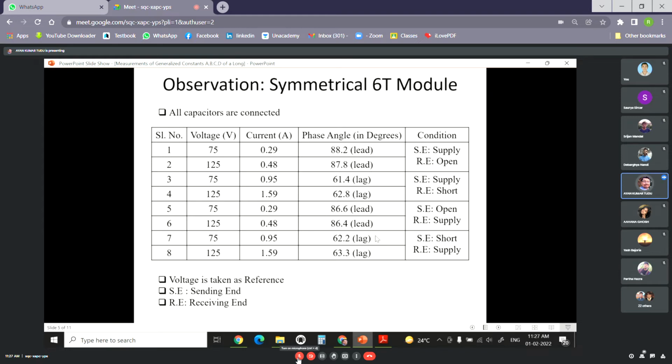Any mismatch of this reactive power balance will affect the bus voltage magnitude without affecting the system frequency. It is very difficult to maintain this reactive power balance because of the unpredictable demands of the consumers, because of which an unbalance always exists between the supply and the demand of reactive power, and there is always a variation of voltages from their respective values.